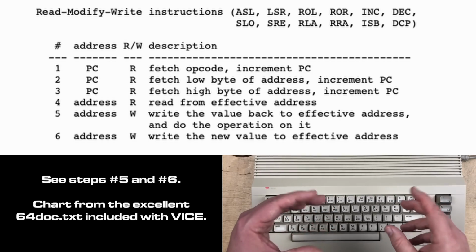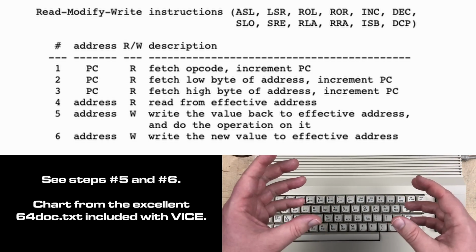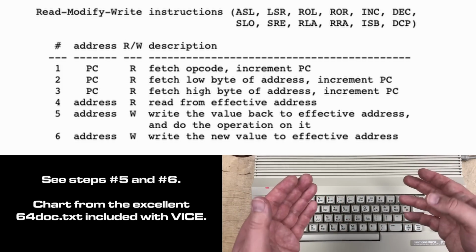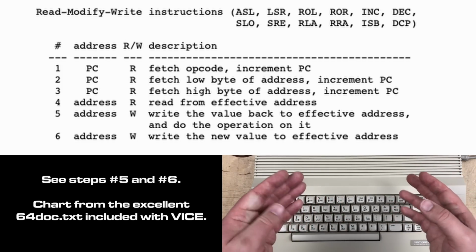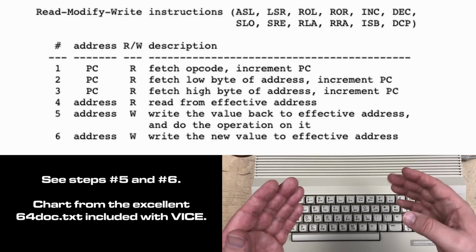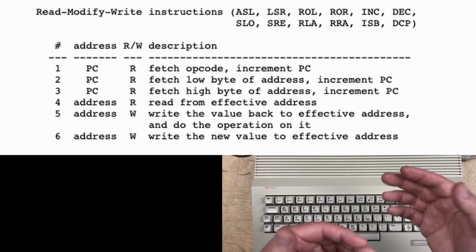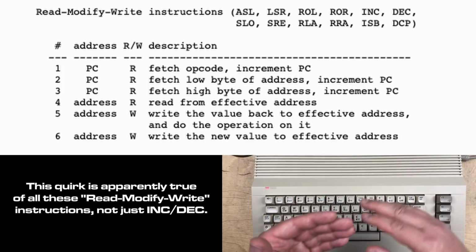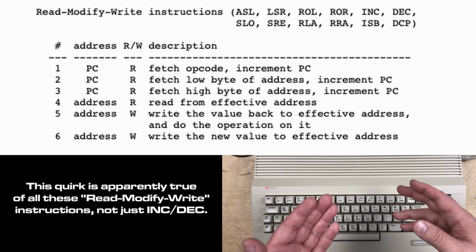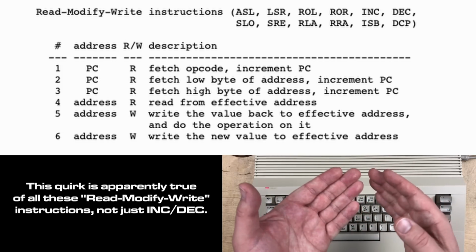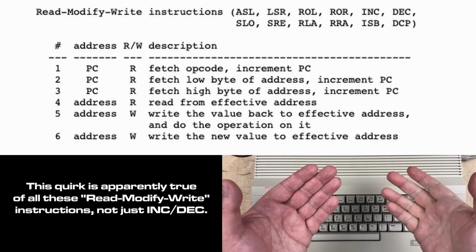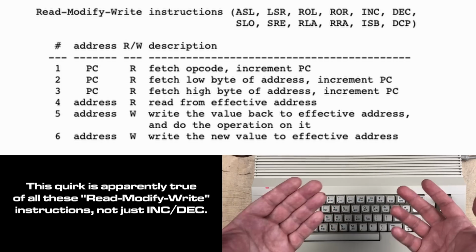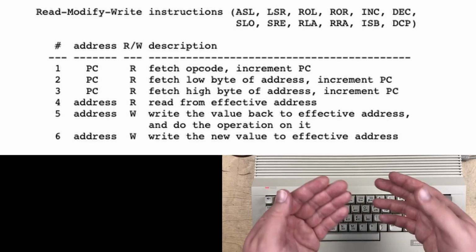The 6502 is amazing at how much it could do for so cheap. It changed the world. But it's not a perfect CPU. One of the quirks is that as part of the way it does the increment, it actually writes the same value twice. And that doesn't matter very much for RAM, on 2 consecutive cycles. I'm not sure if they could have avoided this. I don't think I understand the design of the CPU well enough to know that. Maybe they could have avoided it, but that is what's happening.